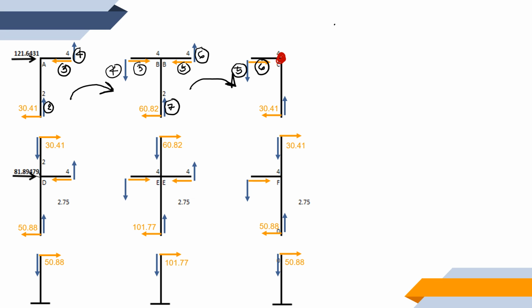Or rather, I got that interchanged. The horizontal force is actually force number 5 and the vertical force is force number 6. Okay, so now at joint C, we will have our focus. So I have shaded that one for you. So notice with respect to joint C, we only have one unknown force, and that is this one. And if you're going to solve or give that